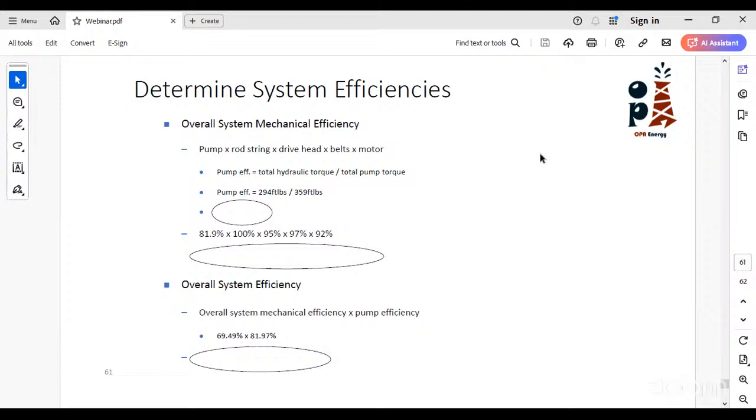These are very important factors when choosing your PCP. Maybe your elastomer can withstand a temperature of 300 degrees Fahrenheit. This is your elastomer. You can say that our PCP can work in this condition, okay? But the bonding material between the elastomer and the body of the stator itself will withstand only 250 degrees Fahrenheit.